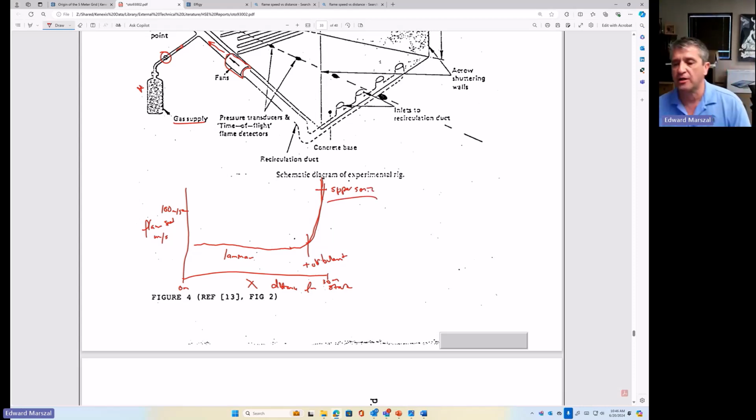Once your flame front goes supersonic, the flame isn't going to travel in a laminar fashion. It's going to be moving faster than the material can effectively get out of the way, and you're going to start building up a shock wave or a shell of compressed gas. So we're really worried about this point where we start to go turbulent and ramp up.